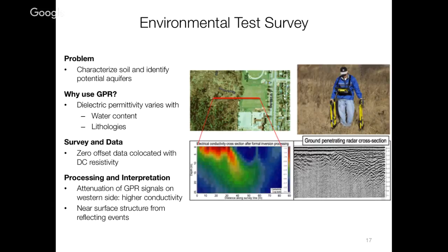So this is depth as a function of distance. And you can see that there's a sort of a high conductivity layer that's coming in here. And so that's really what's masking this. So conductivity plays a crucial role in GPR experiments. If you've got a GPR system and you're trying to use it on resistive ground, you can probably see deep. If you're using it on conductive ground, you can't see. If you put it on the surface of seawater, for instance, you might only get a quarter of a centimeter in to the water.